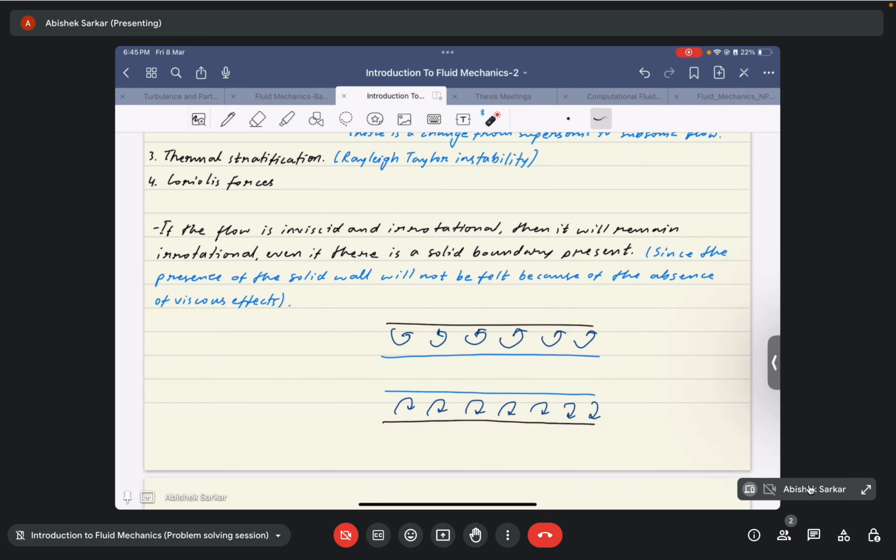Similarly, the river bed would generate vorticity because of the boundary layer effect. But the fluid much above the river bed and just below the upper surface of the river is different. Why the upper surface? Because it is in contact with air, which itself may cause some gradient in the velocity at the interface.